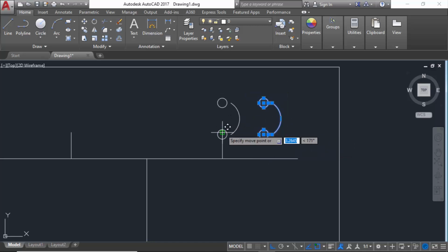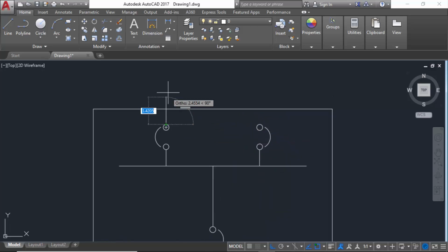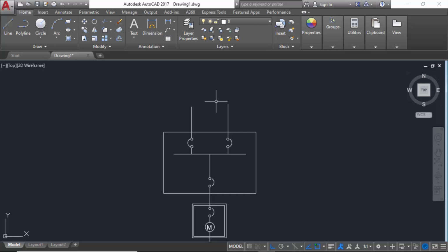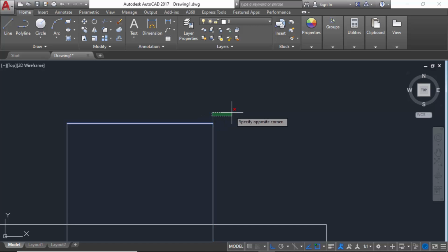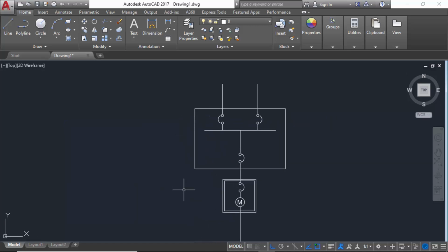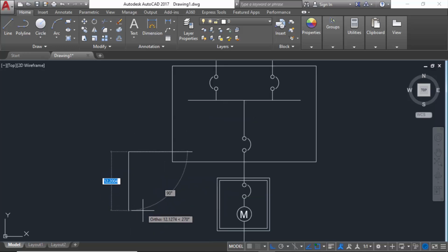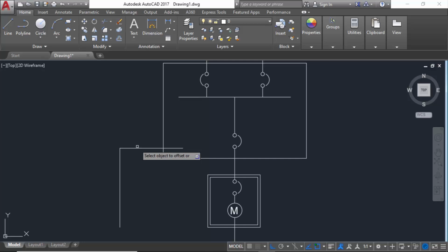From the bus bars you have to connect the MCCB, and then the connection will go out to the DB box, not MDB, DB box. Both connections will go to each DB box in the house, ground floor and first floor. And here we will create the earthing for grounding. This connects to the grounding lug inside the MDB. For earthing of the MDB box we have to create this, and another one for the neutral wire.